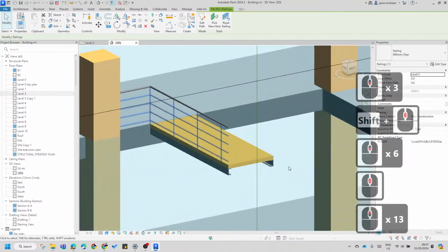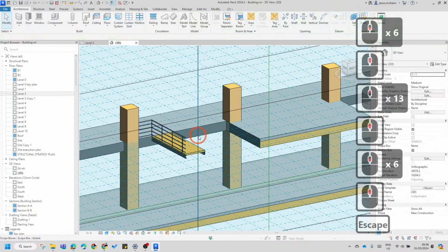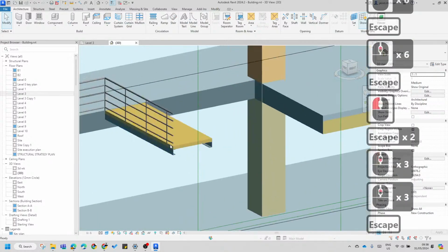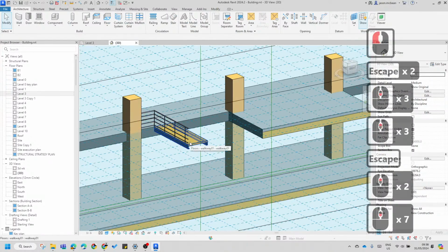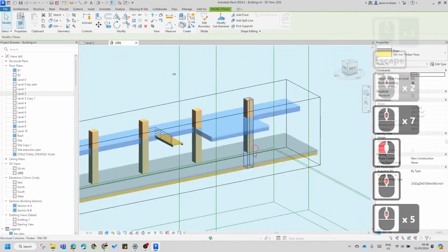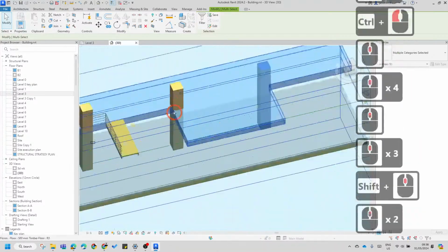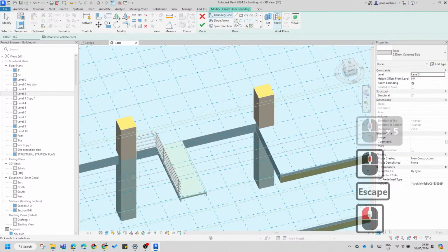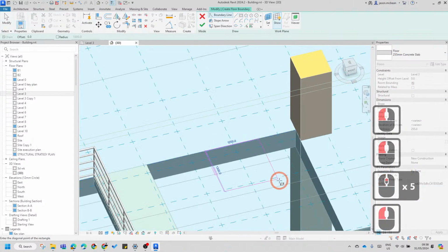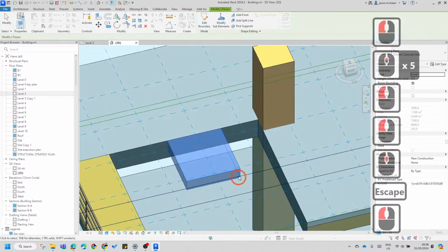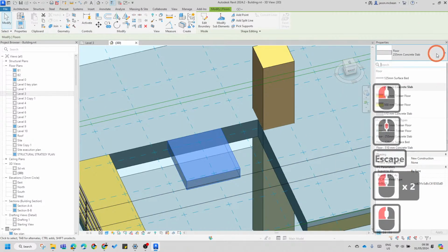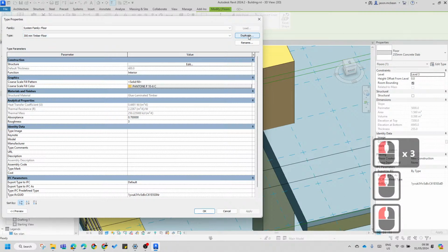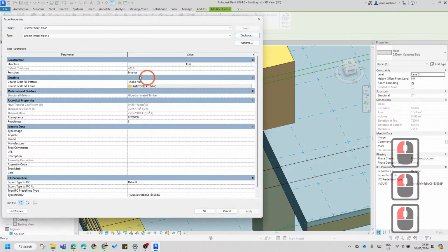Okay. So you can do this method, but maybe for now you don't need to do that, because technically you don't have to. You just create a floor type. So just create a new floor type. I'm just going to create a little nib here and I'll explain why. So floor, so rectangle. Okay, finished. Now this guy, I'm going to go and say edit type. I'm going to go and find this one that I made, timber floor. I'm going to say duplicate. Type 2 is for now.